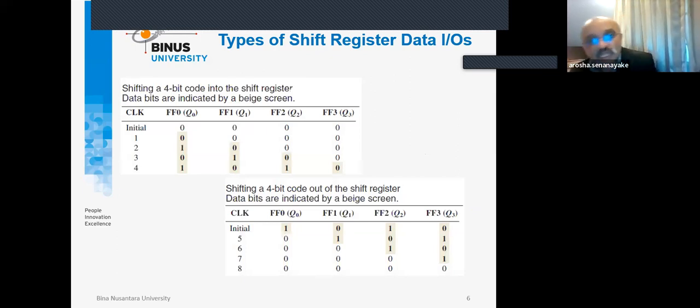So in that manner, you can see that we can observe the movement of the data in such a way that you can see how data is shifting to the right, as highlighted in this case. So then initially 0 is received in the first clock pulse, and in Q0 you find 0, and in the second clock pulse what happened, that 0 is now in Q1, the second flip-flop, but then the subsequent data received for the first flip-flop is 1.